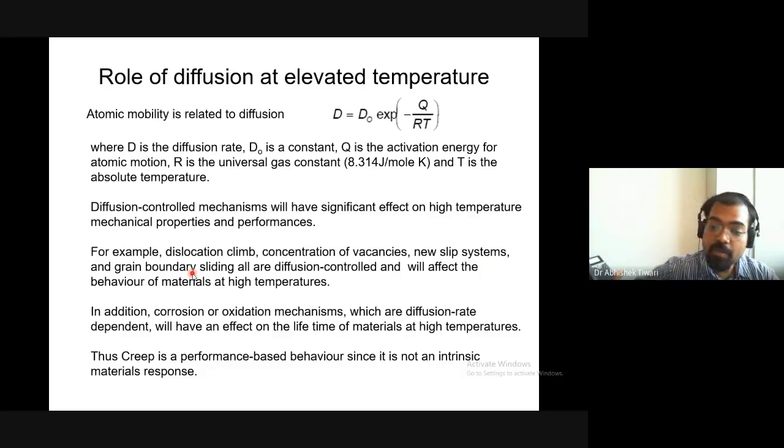and that will be given preference in comparison to iron forming iron oxide. So if you put chromium in the steel, this chromium oxide forms, and this chromium oxide has a Pilling-Bedworth ratio of more than 1, so it covers the whole surface, so no further oxidation of the steel happens. These phenomena happen at room temperature.